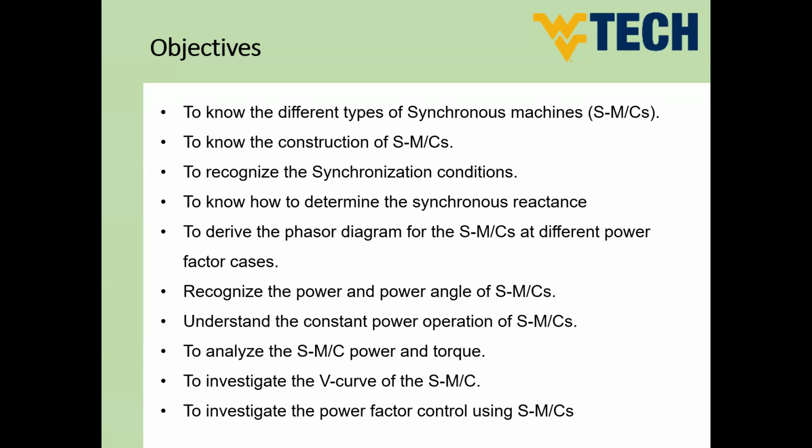We will see that in the specific case of the synchronous motor, because regularly a motor is an inductive load, but the synchronous machine can be controlled to have different power factors. So we'll derive the different phasor diagrams at different power factor conditions, and we will see how to control the power factor.